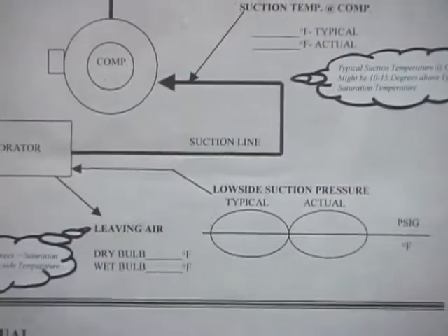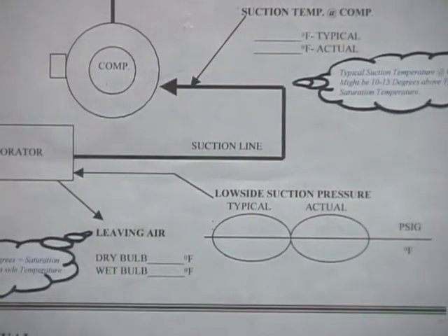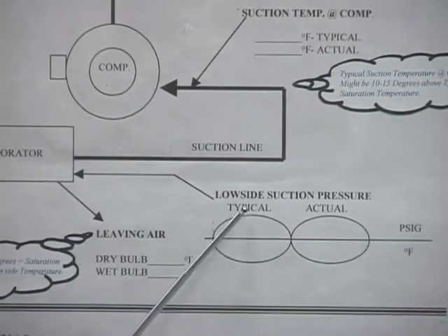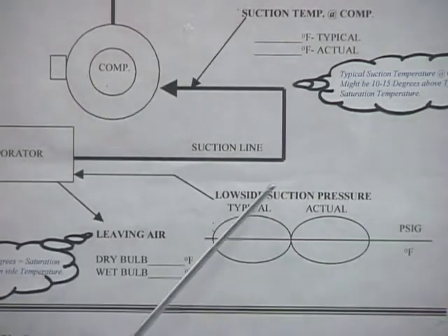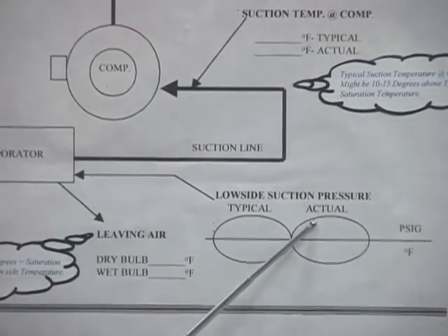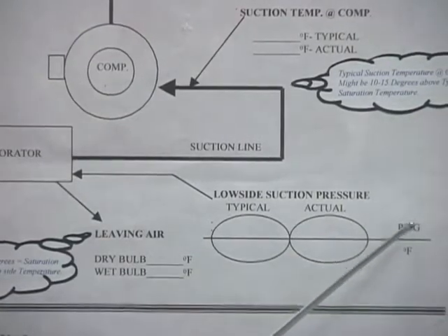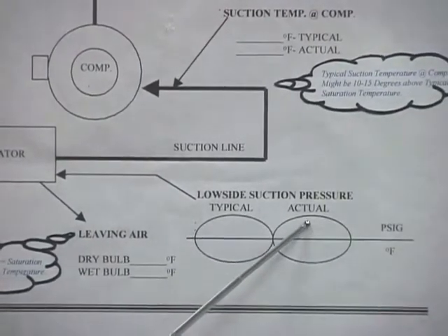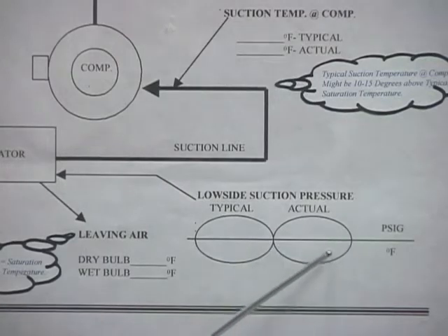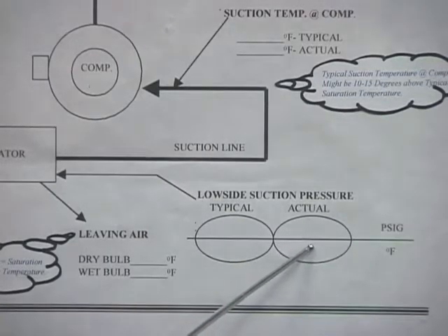Again, you're going to take that from your manifold gauge. We are not worried about the typical at this point. We're worried only about the actual. The PSIG, again, it'll take your low side pressure. You will convert it to a temperature using your PT card.